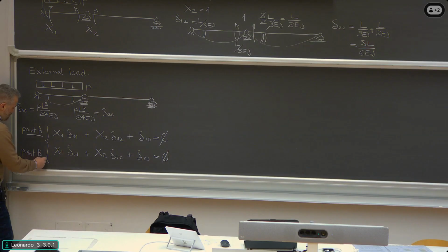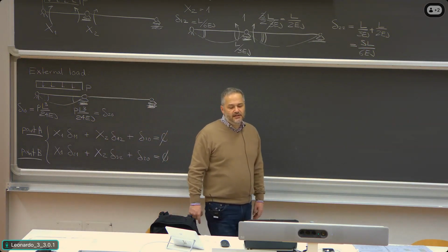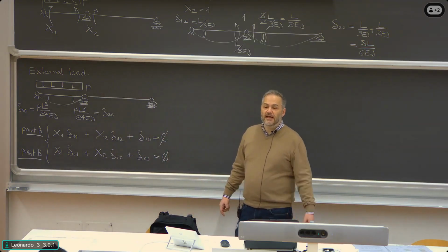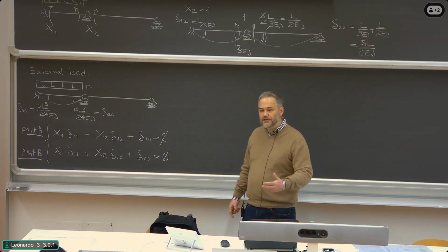And careful, this doesn't mean the total rotation is 0. It means the relative rotation between left span and right span at point B is 0. So no kinks should take place.